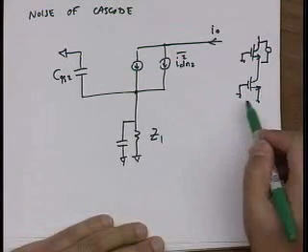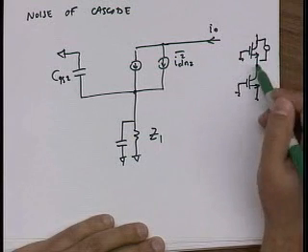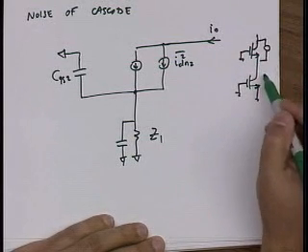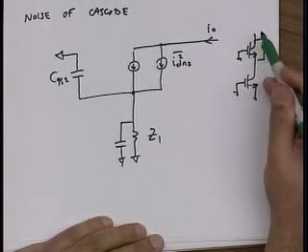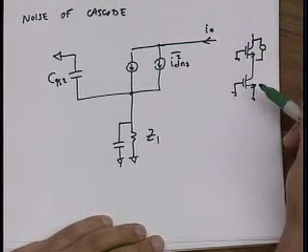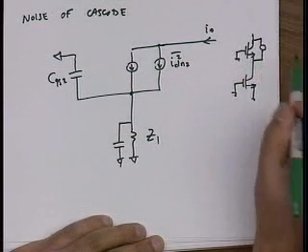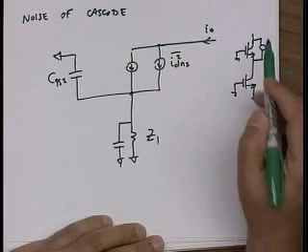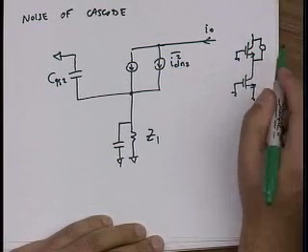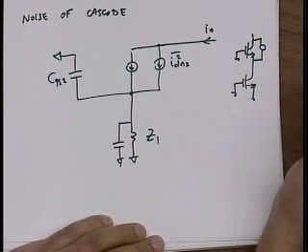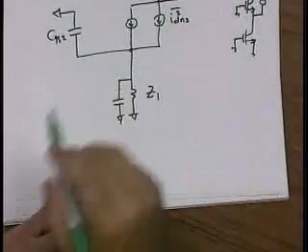Now the noise of this first transistor just goes right to the output. It sees a low impedance because of this cascode, and this is a current buffer, so for all practical purposes, all the noise of M1 makes it to the output. Okay? So it's as if the cascode device were not even there. What's of concern is the noise of the cascode device. And you might guess that the noise of the cascode device is not going to make it to the output. It's just going to circulate inside this second transistor. That's what we'd like to show.